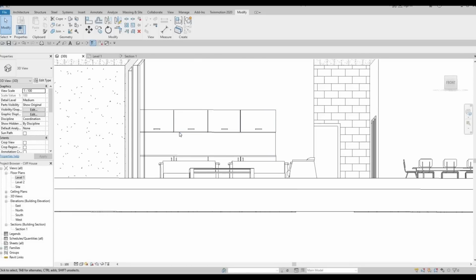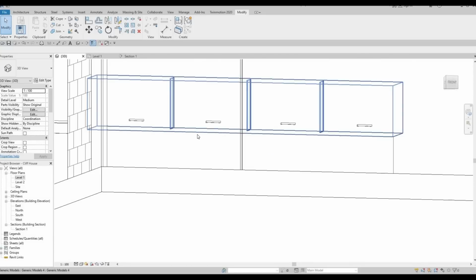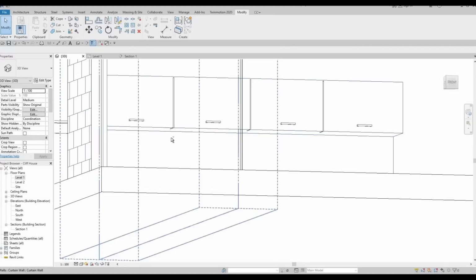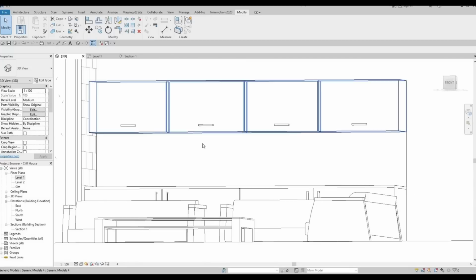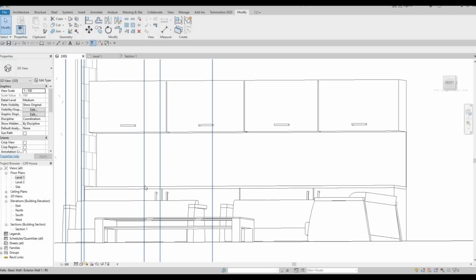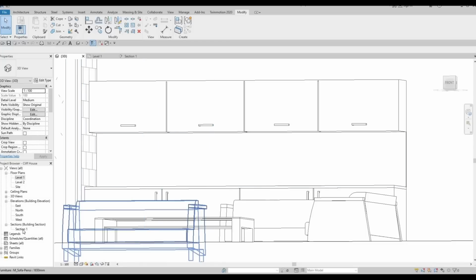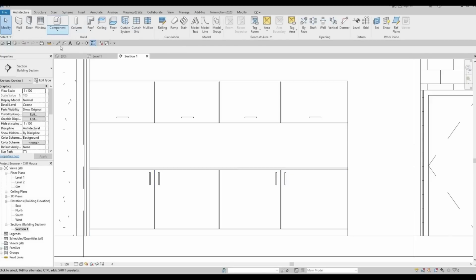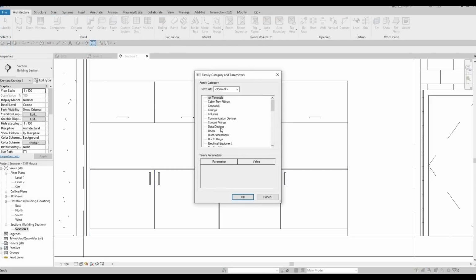And then again, we just need to add in something on the bottom. It's another extrusion, and what that's for is I'm planning to put a neon light under. So a light fixture for the bottom, and I needed something to place it with. So similar to this, we just need to go to section and create another extrusion.